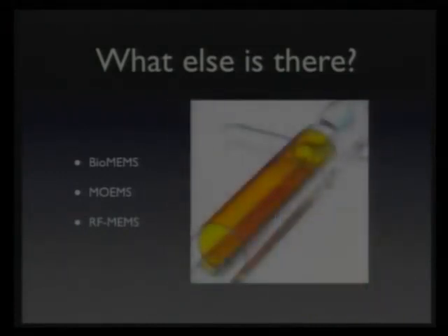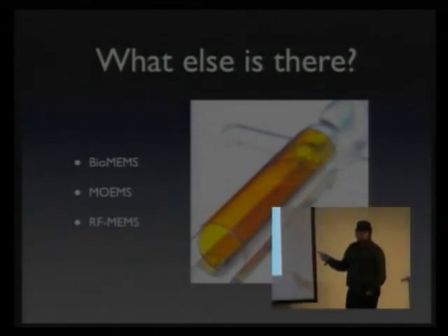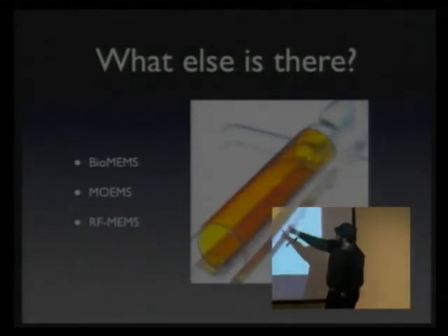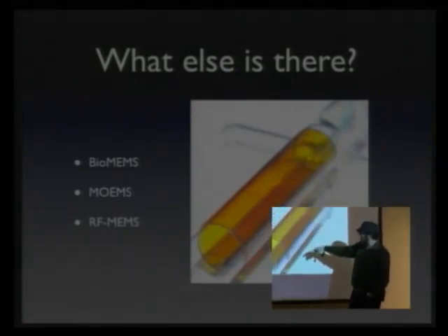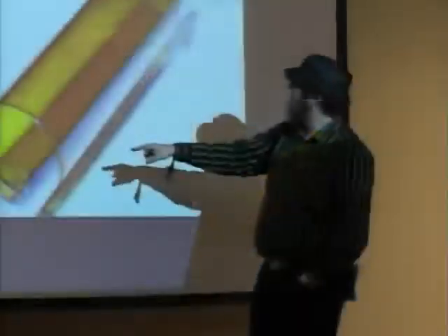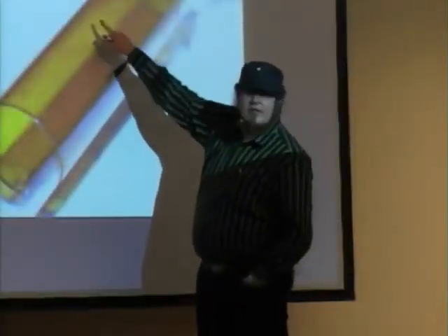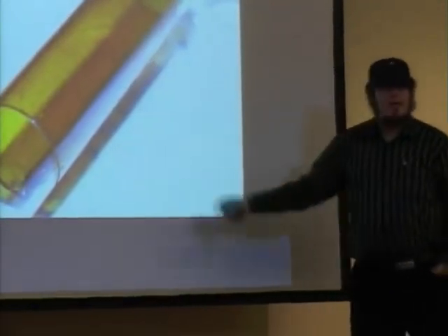And then, yeah, there you go. Here are some RF, not quite yet MEMS. This is one of the processes we had just implemented in Edinburgh. This is a plastic glued onto a glass vial, with some metal tracks. I think you can see them. And they are not made in a conventional way. They're laser direct written. It's really nice, so you can write metal tracks onto plastics with a UV laser, if you're happy to have one.